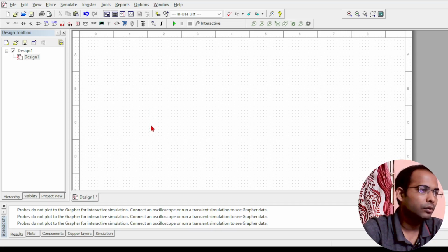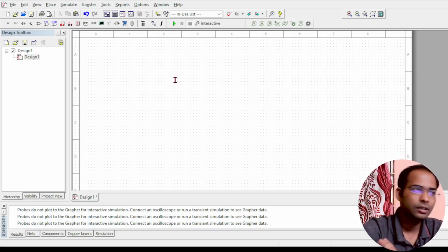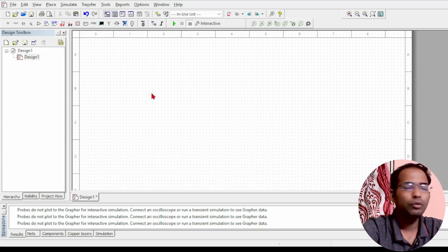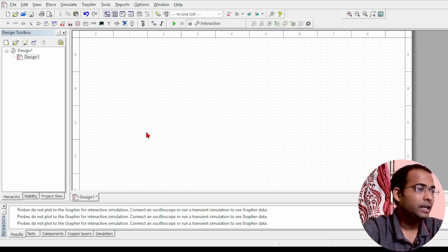Then you will find 7404, which is an inverter, which you can basically consider as a NOT gate. Then it is an AND gate. So all these gates you can use, but for simplicity, what I will do here is go to all groups, and here I'll just write AND. You can go with the ICs, that's not a problem. So here you see AND2 means 2 input AND gate, then 3 input AND gate, 4 input AND gate, and up to 8 input AND gate is there. But we will be using just 2. So just take the AND gate here.